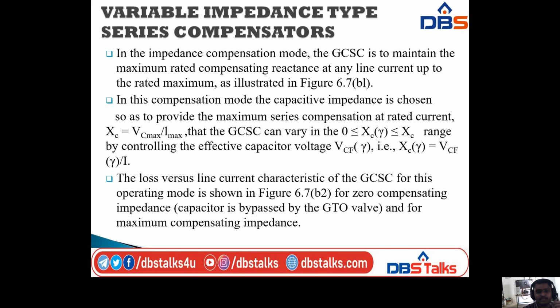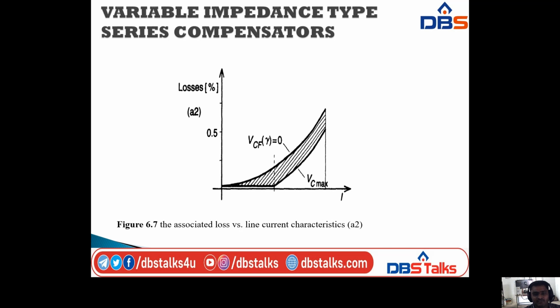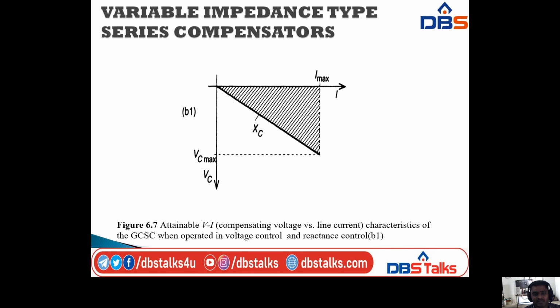Next, in the impedance compensation mode, the GCSC maintains the maximum rated compensating reactance at any line current up to the rated maximum, as illustrated in this figure.